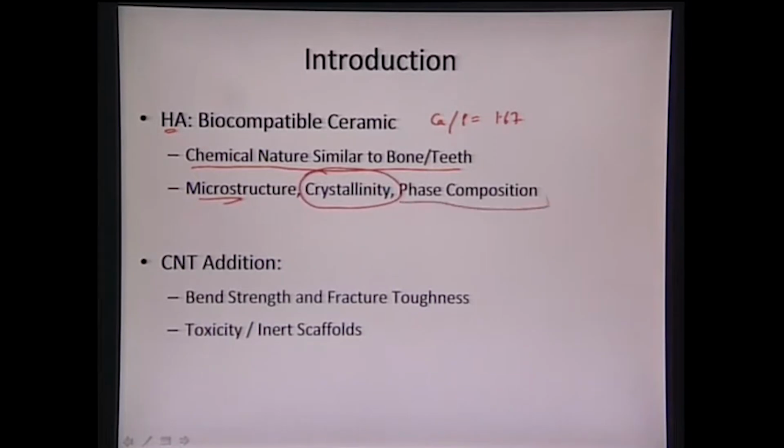Also, the kind of phases generated after the processing can impart very different properties to the hydroxyapatite. It can also lead to some degradation of phase and change the percent of crystallinity. Those phases can be degradable or non-degradable. So we need a proper combination of those phase compositions in the hydroxyapatite even after processing.